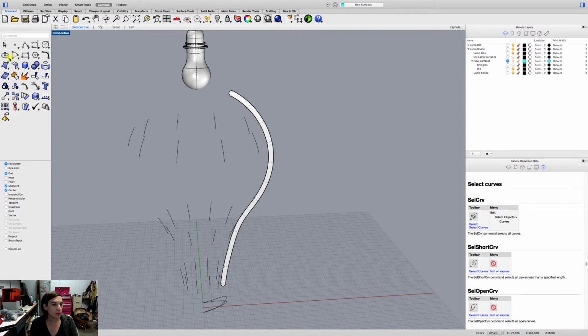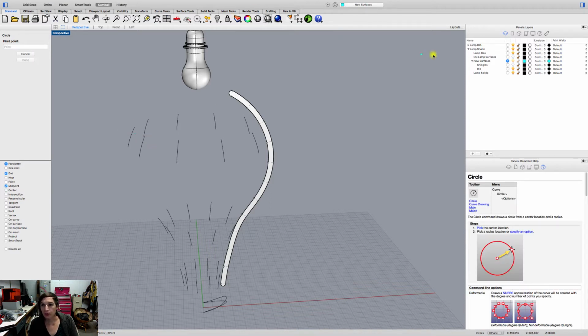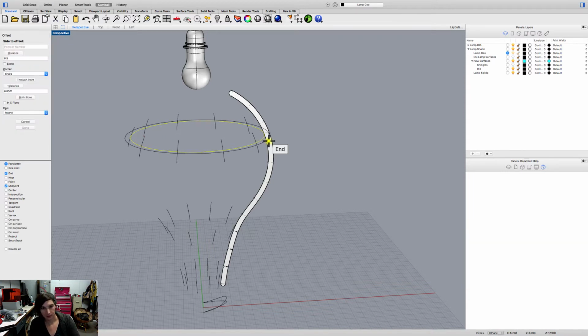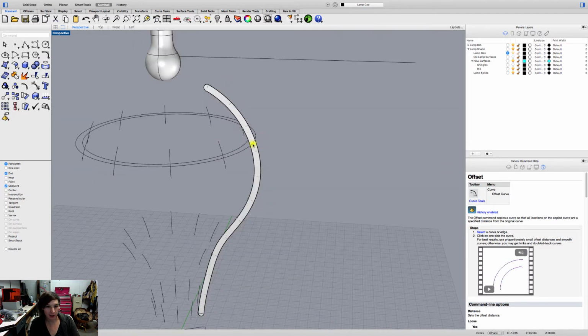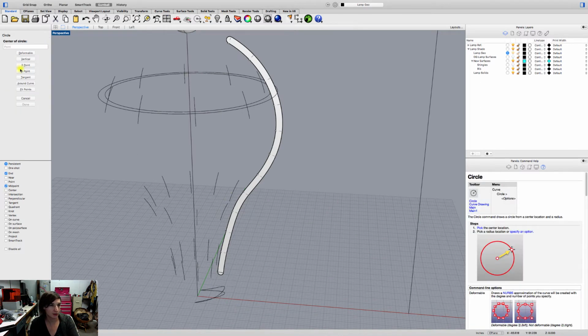So now what I'm going to do is pretty straightforward to add those curves. I'm just going to come up to Circle. And we can just do 3 points. And midpoint. And we'll do, well, why don't we work in lamp geometry? And then it really doesn't matter which 3. They should all be the same. And then I'm going to offset that the 1/2 inch. That way it kind of lines up here with that one. And I'm going to do the same thing with these other 3.